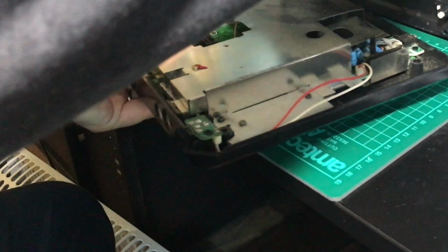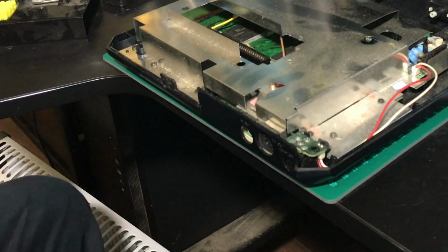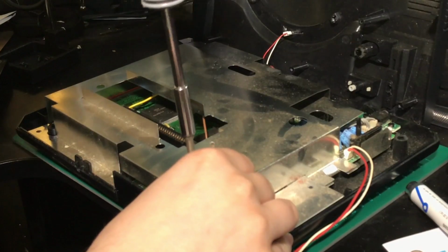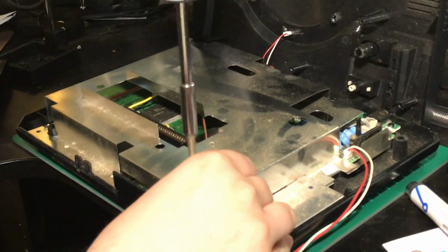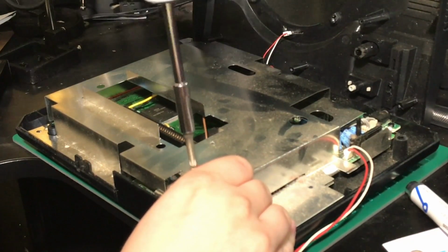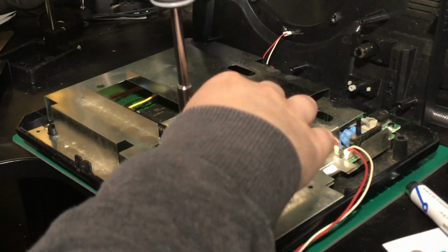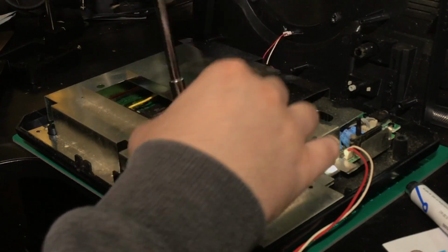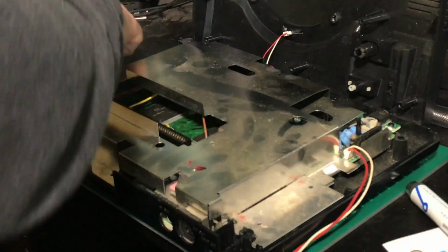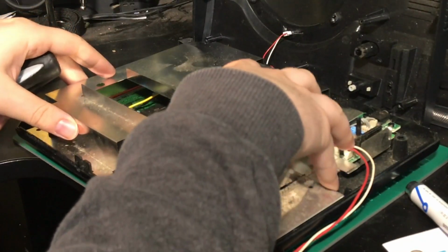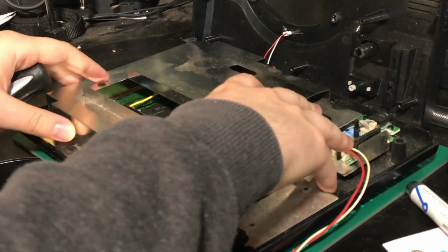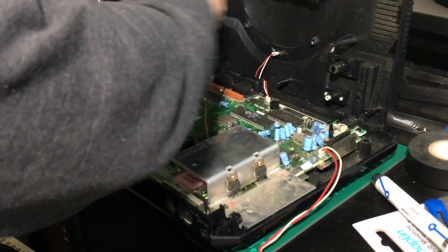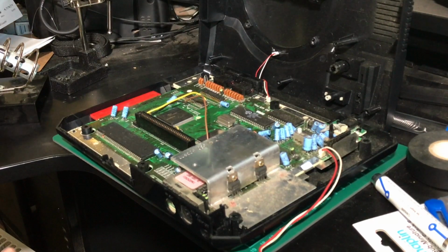If you do decide to remove the LED, make a note of what coloured wire corresponds to which leg of the LED. Now you can remove the screws that keep the metal shielding in place. Once again, make sure these screws are in a safe place, and it's also worth remembering or making a note of what screws were in what holes, as 2 of the black screws are of different lengths and there's a silver screw that's covered in some sort of red glue. Once unscrewed, carefully remove the shielding and you should now be ready to start modifying your system.